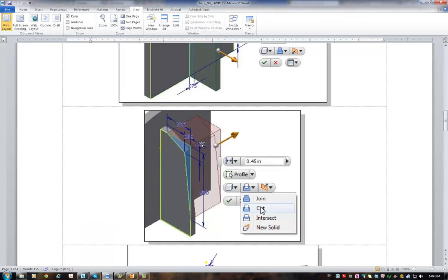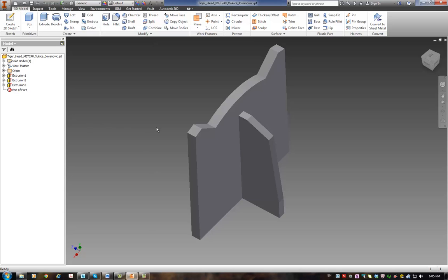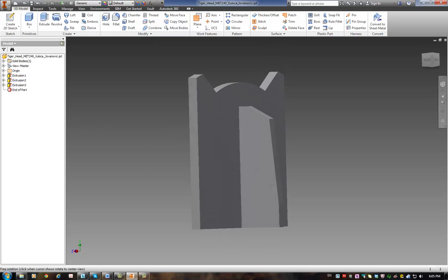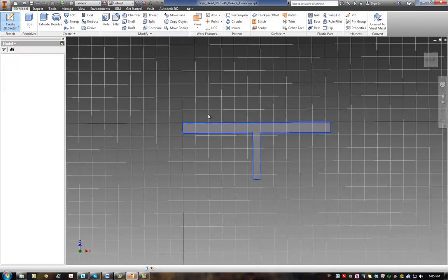And now when I finish that, I would like to add these 2 circles down. So you see the circle diameter is 1, and it is from this side 0.5, and from this one 0.167. And there are 2 of them. So that's the thing I will add next. So I will again press the Shift key and turn this around so I can select the plane that I need, which is this one. And I will go Create 2-dimensional sketch, select the plane.